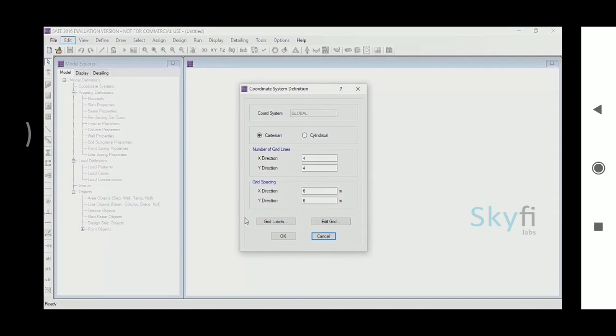You will first draw the slab of the building plan, and then extend equally on all sides to make the footing. The building slab is of 18 by 18 m dimension. Note that you will draw the building slab, of 18 meters by 18 meters dimension, with the grid. You will then extend it, for the mat footing slab later.